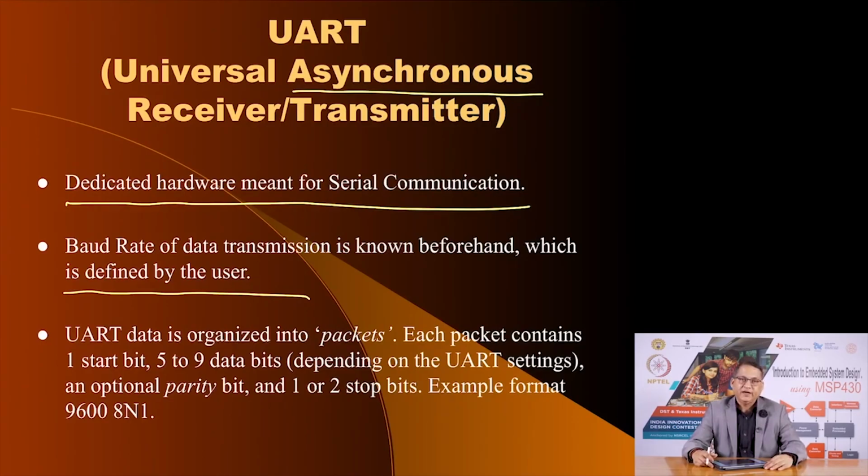Also, since you are sending data serially, for historical reasons, in the olden times you did not want to send 8 bits of data. In fact, if you recall, the original ASCII standard is defined for 7 bits. So if you wanted to send ASCII information, you only wanted to send 7 bits. But these days you want to send the entire 8 bits of data, and in fact there is an additional advanced ASCII format which allows for 8 bits, and so you may choose how many data bits will be sent in each transmission, and together with the rest of the bits we call this one data packet.